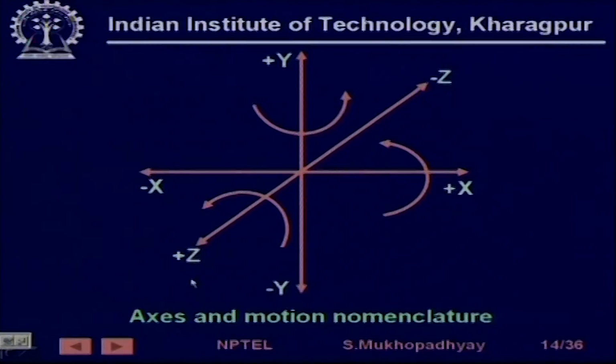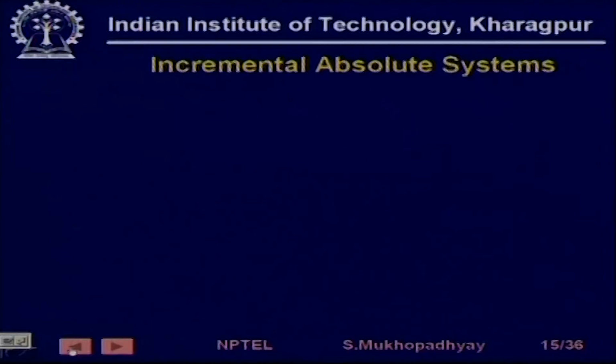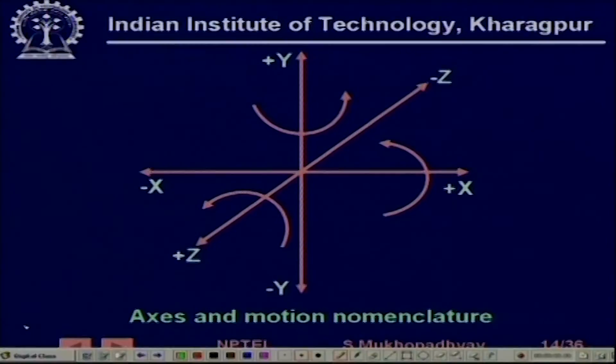It is fundamental to define coordinate systems because all the part program instructions, especially the main cutting instructions, involve various coordinates. The coordinate space is actually very simple. It is like x in this direction, y in this direction, and it is a right handed coordinate system. Therefore, z will be the vertical direction.